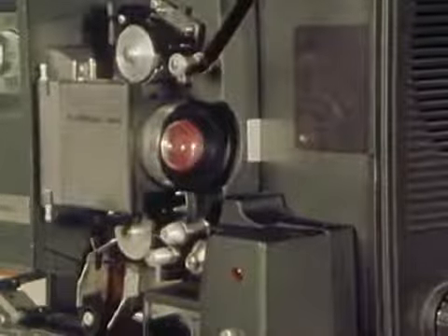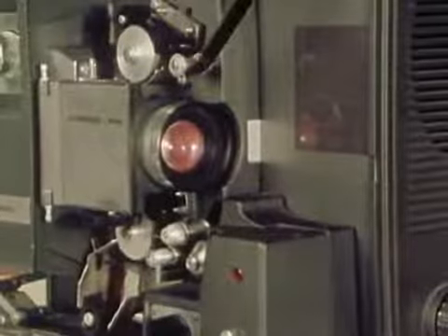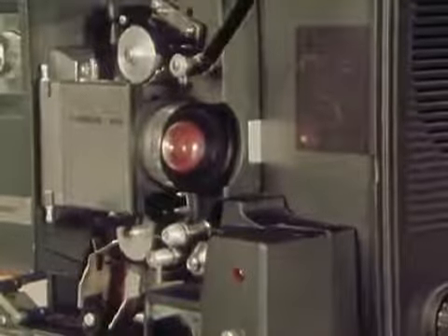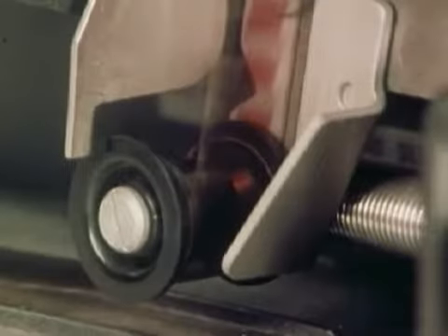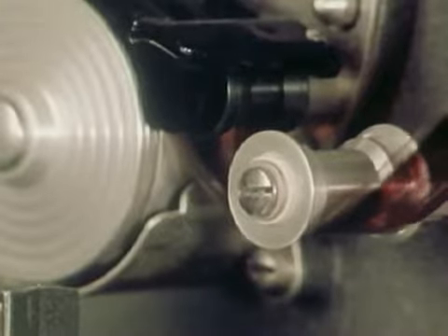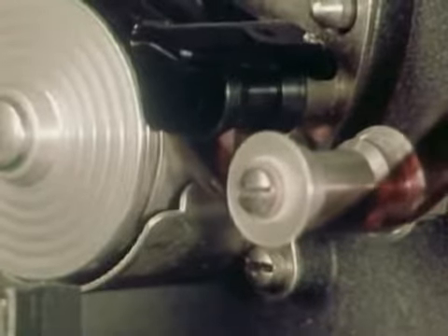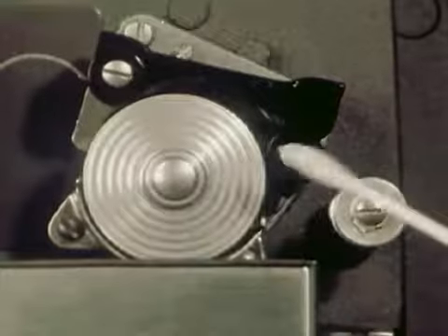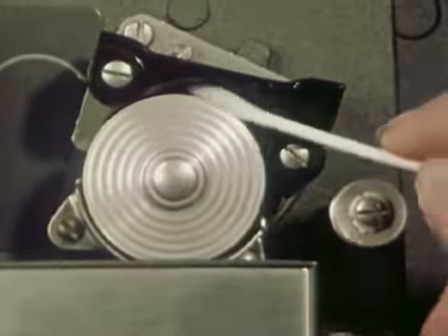This fuzz around the edge of the picture area is dirt in the aperture. It is not only disturbing to see, but it can scratch the film. Though projectors are built to keep film wear and strain at a minimum, film running through a projector must touch hard surfaces in a few places. Any dirt, grit, or caked emulsion in these places, such as the film gate, the sprockets, which engage the sprocket holes and move the film, and the guide rollers, can cause these harmful and unpleasant scratches. These areas should be cleaned before every film showing.